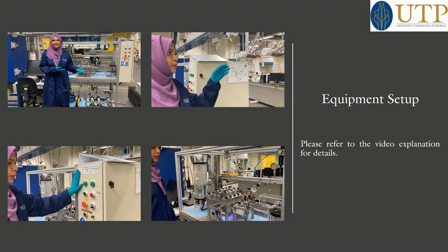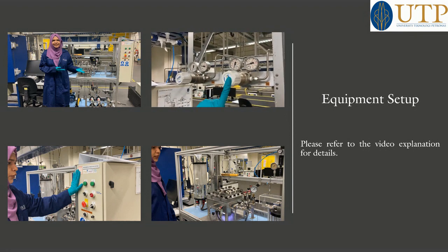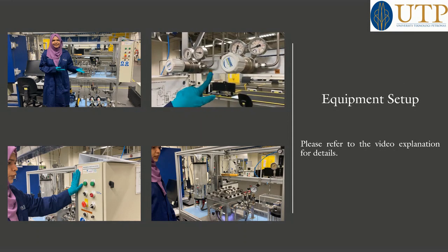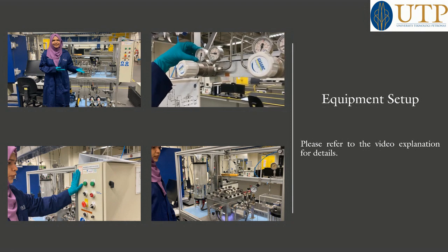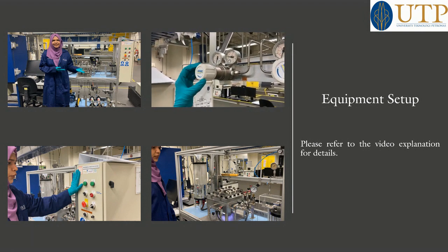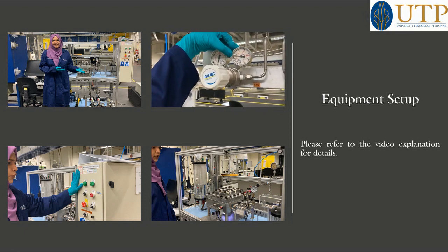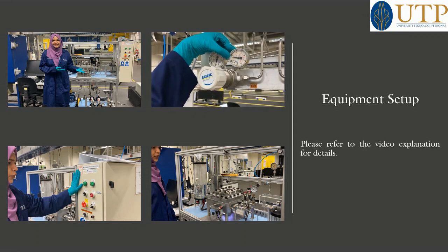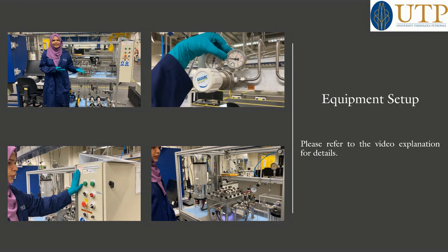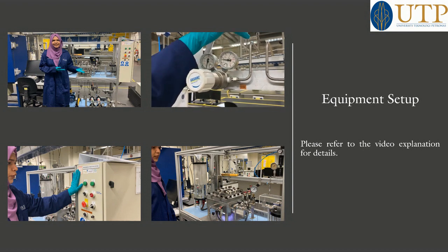Firstly, I would like to talk about this pressure maintaining valve. The first one is for nitrogen gas and this one is for carbon dioxide gas. This one will indicate when you increase or decrease the pressure. And you can see that it's indicating the pressure is 700 psi. That means this pressure we have already given in the cylinder. Our cylinder is placed outside the lab and it's connected with these lines.